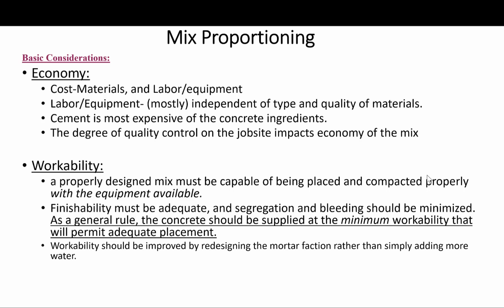Redesigning the mix, taking advantage of the available admixtures that help improve workability, will go a long way. Cooperation between the mix designer and the contractor is really essential to ensure a good concrete mix. In some cases, a less economical mix may be the best solution, because we do not trust field practices 100%.